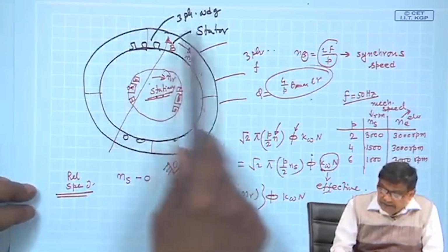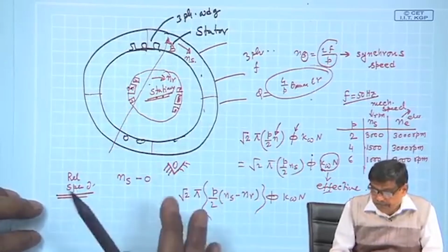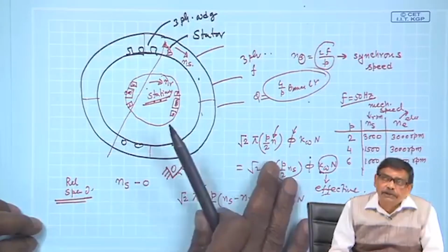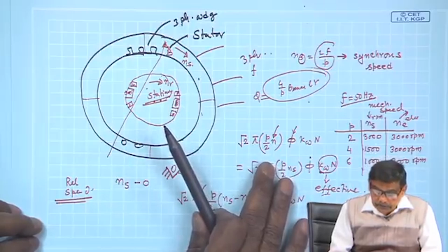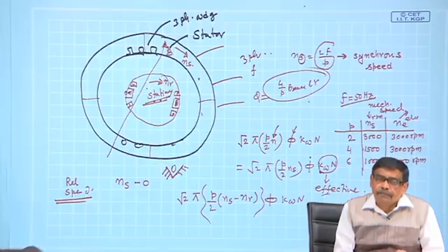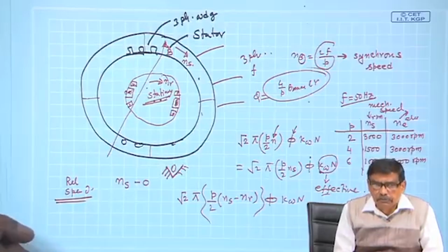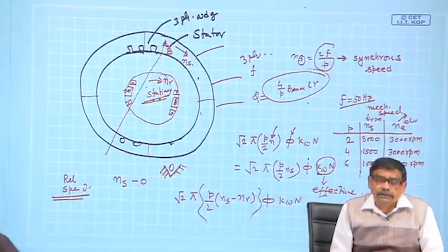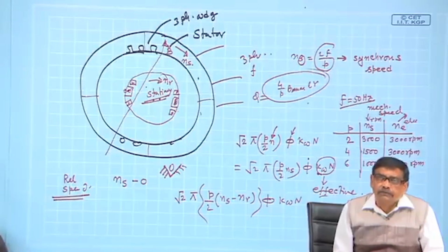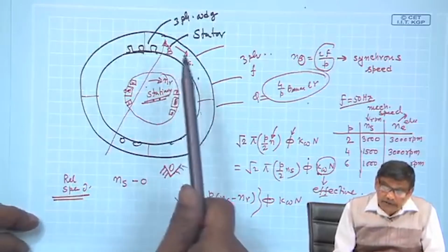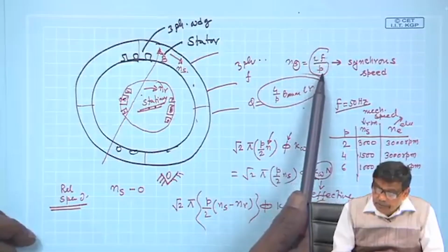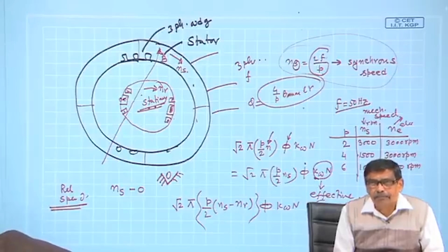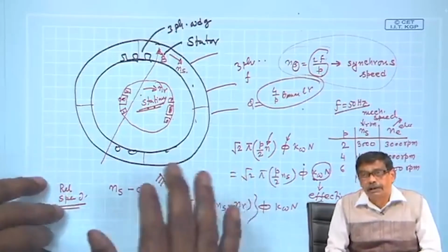Therefore, these are the things you please go through very carefully, and always remember, while specifying the speed of a rotating magnetic field, it is good practice to always write down that this is with respect to this fellow or that. In general, the speed of the rotating field depends upon supply frequency, which is 2 f by p, and it is with respect to the structure which houses the winding. Thank you so much. This is an important lecture. Please go through it.